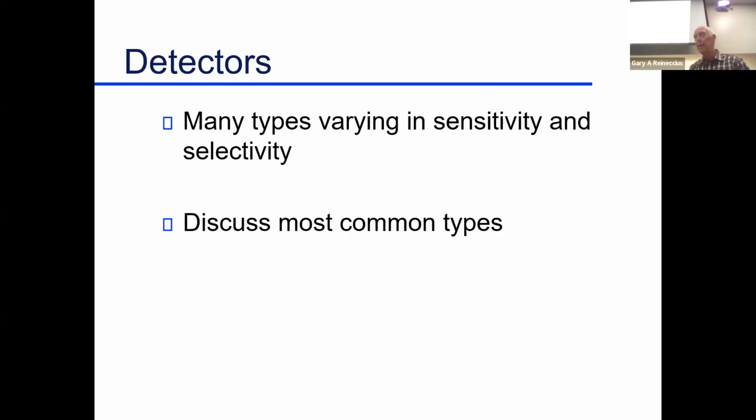So we've got our injection, we have our separation. Okay, now we've got to detect whatever. So this is turning compound into an electronic signal. And there are several different kinds. The workhorse is flame ionization. So you simply burn whatever comes out of that column. It goes into a hydrogen flame, gets burned, ionized, and you measure the ions. Okay, that's a workhorse. But again, there are several different approaches, and we'll just simply mention them now.